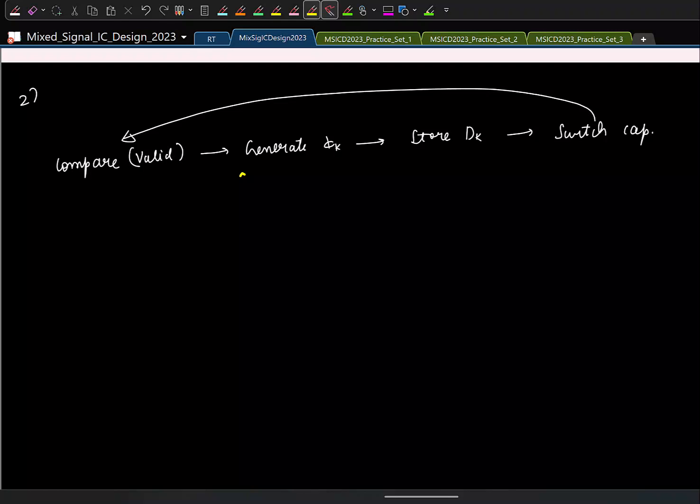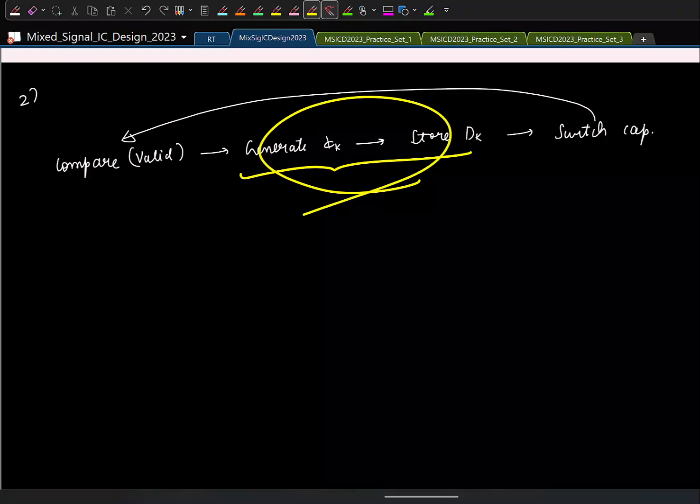So let us say I want to get away with this delay. I don't want to do this. So how can I not do this? What should I do? Exactly, and not alternatively, but that's the point, right? Here we are basically doing this because we are using the same comparator for all the n comparisons. If I don't want to do this step, for doing n comparisons, how many comparators should I use? N comparators, right? Every comparison I will do using a separate comparator.